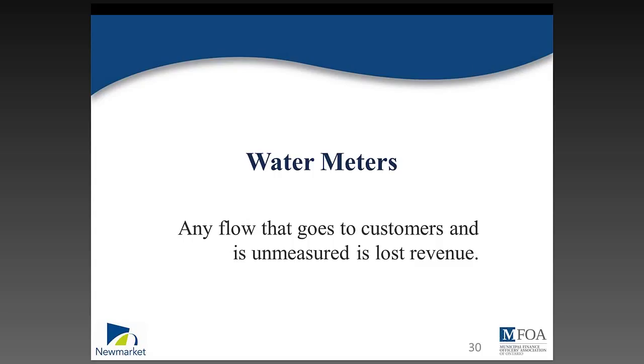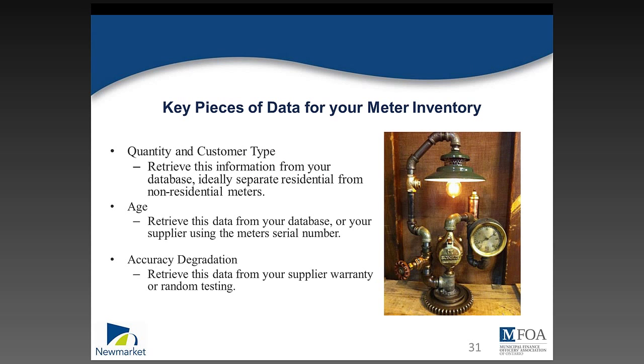So it goes without saying that meters are an essential part of tracking water consumption. However, I have found that many municipalities do not pay as much attention to them as they should. If meters are neglected and not properly maintained, they begin to slow down. This means they begin to under-register and you lose potential revenue. To get started on taking better care of your meters, you need to know a few basic things. The 3 key bits of information you need to know about your meters are quantity and customer type, age, and accuracy degradation.